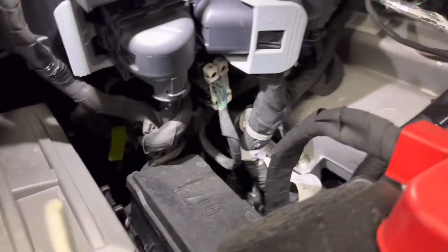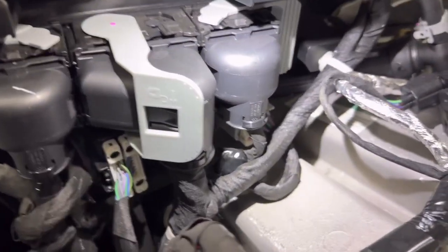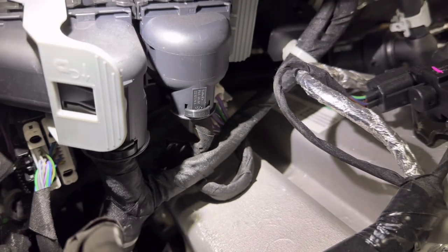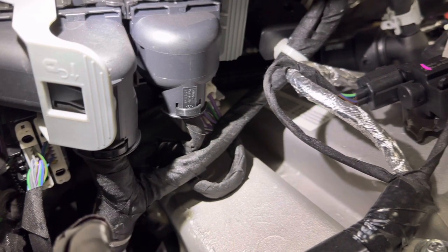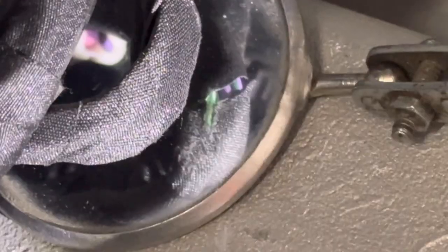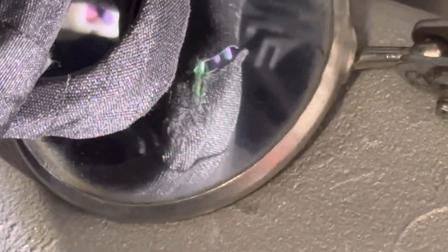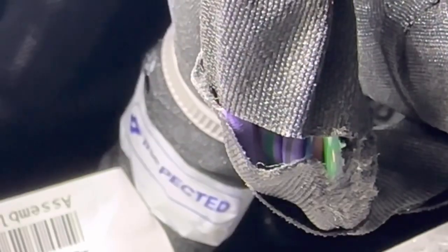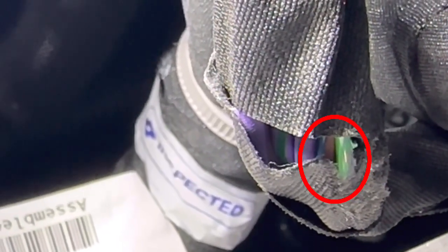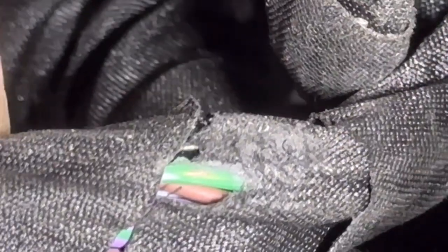With only 146 miles on this vehicle, I think I probably got a little bit of tunnel vision. I was expecting a misrouted harness melted on the exhaust down below or something along those lines. I wasn't looking as closely as I probably should have been for a harness with a spot already shaved through it. But after sliding a mirror between this harness and the valve cover, that green wire with the white tracer is the high side of our powertrain network. And the shiny spot on it that the camera doesn't want to focus on is bare copper where the valve cover has rubbed through it.